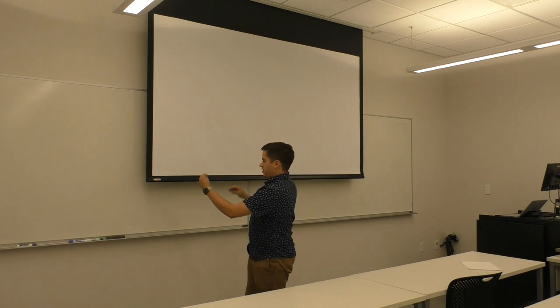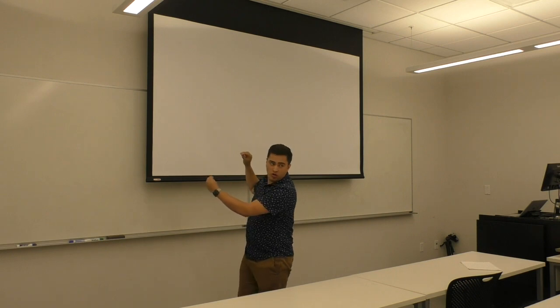Just my question. Did they actually redesign the blade because you suggested they increase the pitch, right? Yes. So they actually got a new blade design? No, they use the original blades. The best way I can describe it is that they had a cutout and you would change the position of the bolts holding in the fan blade. So you would have one bolt here and one there, but there's another hole cut out to re-bolt it higher up. Adjustable. Yeah, so between 10 and 15 degrees, you were able to adjust it.